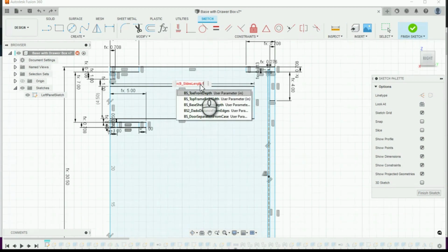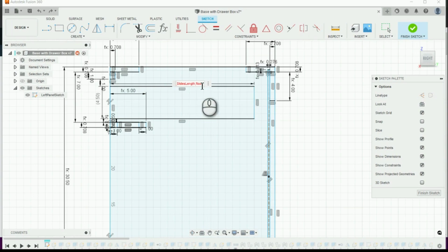We are going to use the floor operator, open a parenthesis, and we are going to calculate now the depth of the cabinet minus the nailer thickness minus the back material thickness minus some space that we need on the bottom, on the back, which is going to be for now 1/2 inch. So we close this, and I need about 3 parentheses to close everything, and I'm gonna hit OK.